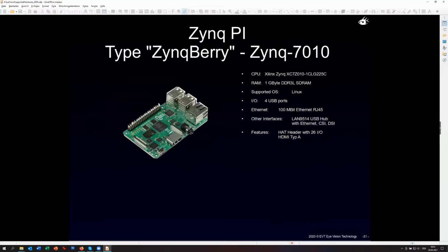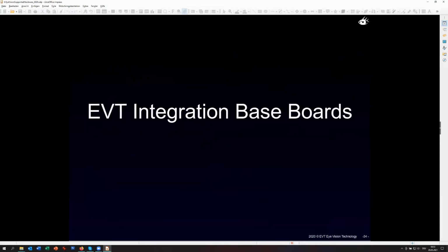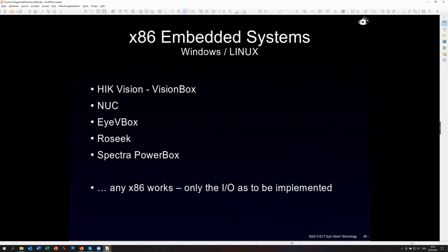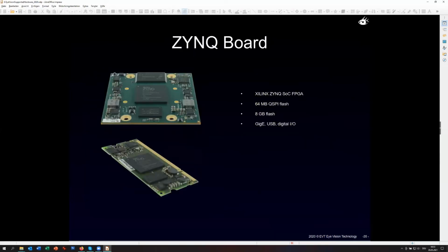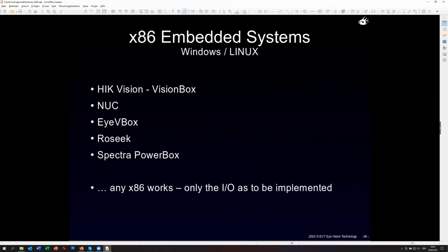The communication to the robot is mainly done based on either XML or ASCII-based communication. So there is no real reason to prefer TCP/IP or RS232. Both work, and at the end it's only a question of speed and what works better. Nowadays, if you use XML, it's the best, as long as the robot supports it.